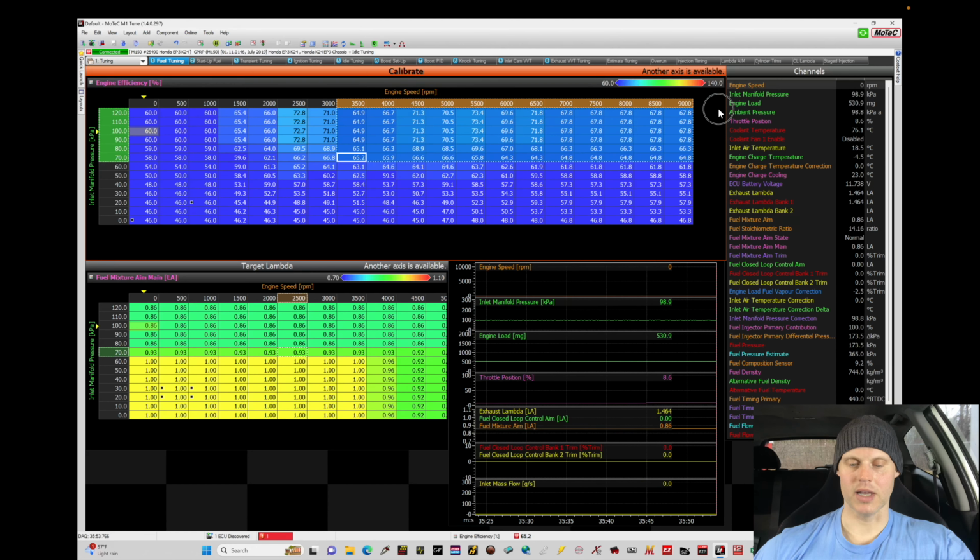We're going to go in and have to completely redo the upper area of the table here to suit high cam activation. We have to be careful with the way we engage VTEC. We don't want to engage too low of a manifold pressure and too low of a throttle angle. That'll start to decrease the drivability out of our engine, but it also will be really hard to try to dial things in because you're not going to have a clear line of where the engine's on low and high cam within this VE table.